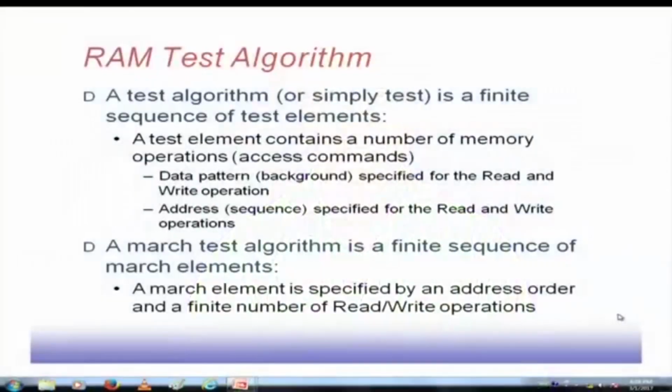So, we have been talking about RAM test generation algorithms, like how to generate the test patterns for RAM, what should be the technique. And this test generation algorithm essentially comes with a set of read write sequences. In fact, for testing a memory, ultimately we need to write some bit pattern there and check whether the bit pattern has been correctly written there or not by doing a read operation.